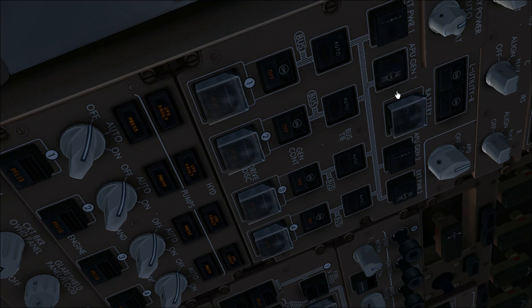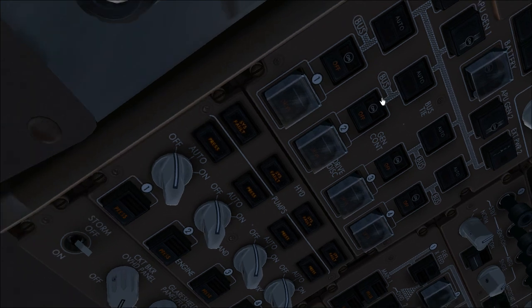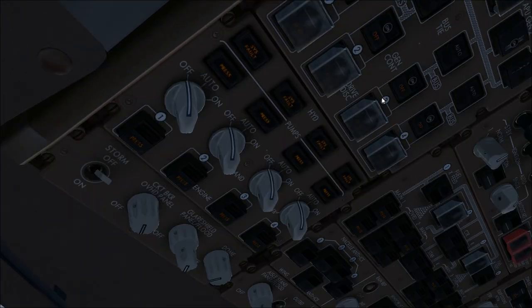Anyway, now we have the available light. We can select the APU generator. The aircraft automatically disconnects the external power and connects to the APU while depressing the button. Next part of the checklist is the hydraulic system and hydraulic panel. We have to check the demand pump selectors are all in the off position. They are all in the off position, and the system full and system press lights are on, as checked before.